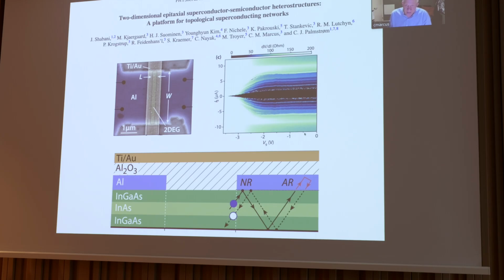So as you go negative on the gate voltage, it covers the exposed semiconductor, you deplete and shut off the supercurrent. This black region in the middle, surviving until about -3 volts, is the supercurrent. And here's the supercurrent that then shuts off at the peak voltage.